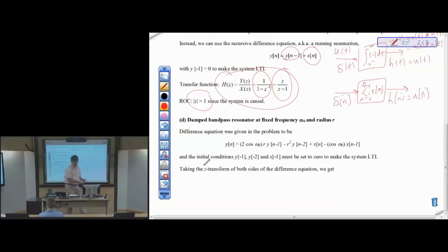Okay, the integrator is really useful in many ways. Keeping track of a measurement over time. This is also known as a running sum. A way that you can compute an average is keep a sum of all the measurements until you finally need the average. So you have two memory locations. One keeps track of the running sum. One keeps track, as a counter, of how many samples you've received. When you need the average, just divide the two.